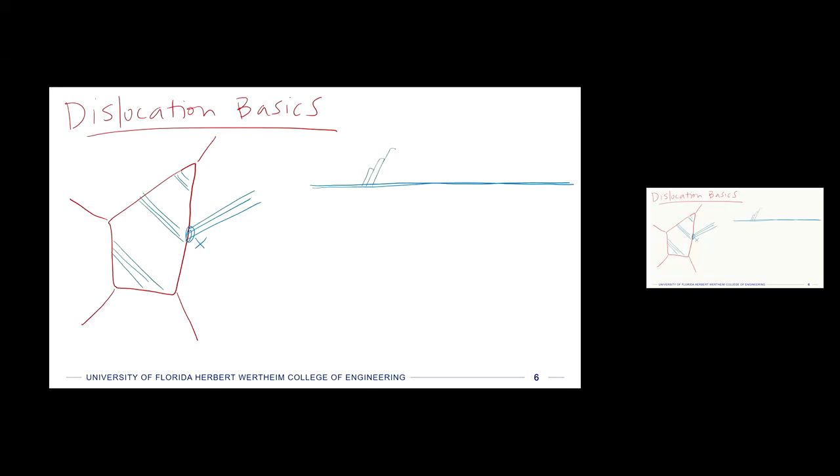And this is also at the molecular scale. So the material will pop up above the surface like that, and you'll get these little projected bits. And what really is happening is that is a slip band that goes way deep into the material, but you just see it at the surface because you started with a very flat surface. So those things tend to stick out. So that's one way that early scientists visualized these things.